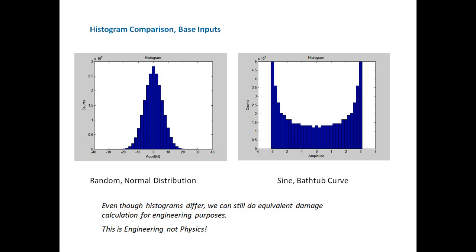It's comparing apples to oranges. And as we look at this random, the levels tend to fall near zero, but there is a distribution, and there are some peaks that go out to 3 sigma, even 4.5, 4.6 sigma on either side. Whereas with sine, the levels tend to stay near the peak positive, peak negative values with well-defined limits with a fairly rapid transition in between. So the fact is, random and sine are two very, very different environments.